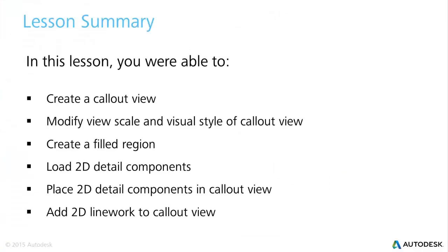Let's review the learning objectives for video 3. In this lesson, you were able to create a call-out view of the model. We then modified the view scale and visual styles of the call-out view. We further iterated on the detail view by adding filled regions for the earthwork. We loaded in 2D detail components to further illustrate the structure of the detail view, and then added 2D detail line work where necessary.